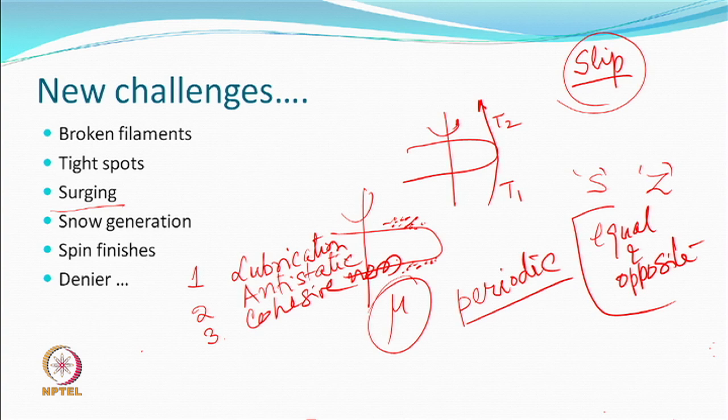The denier. So, denier normally should not be any difficulty in finding out. In the earlier case, there was no issue anyway. The moment you do draw texturing, you start with a denier of a POY and end up with the denier of a textured yarn, and we hope that they will be correlated with the draw ratio.